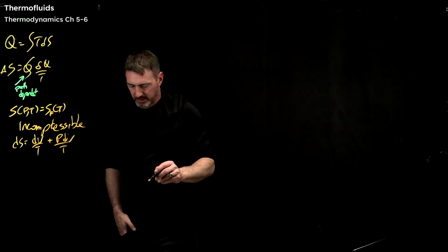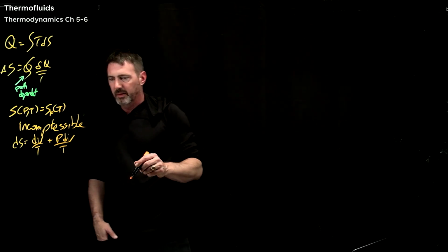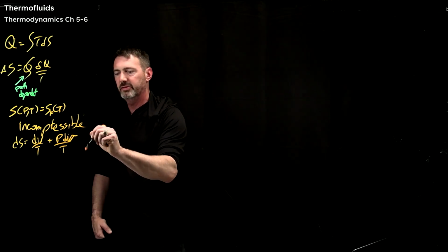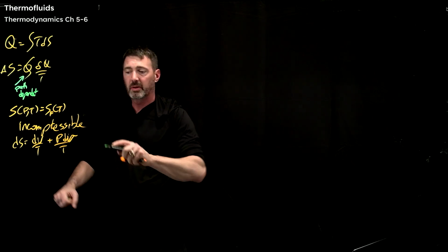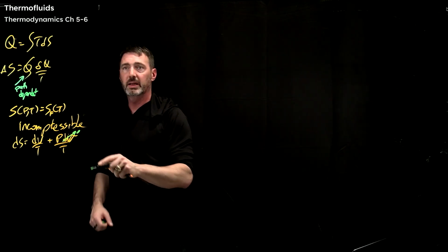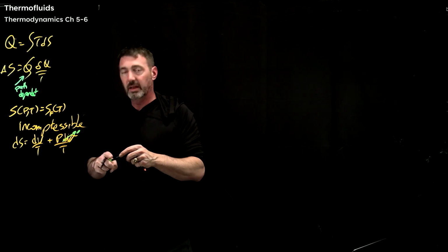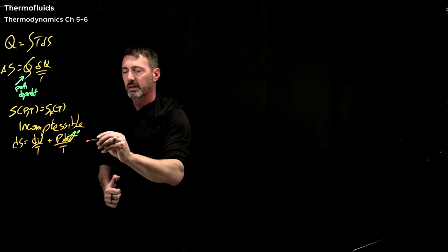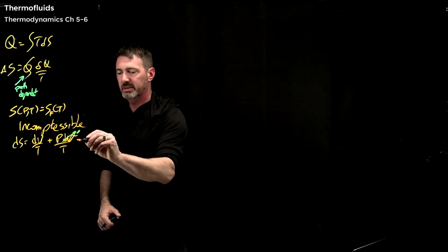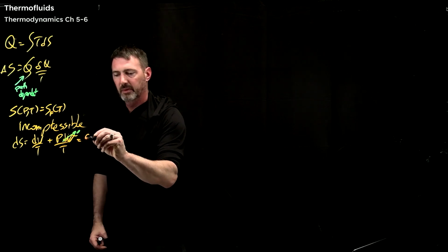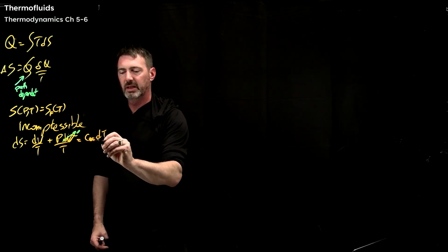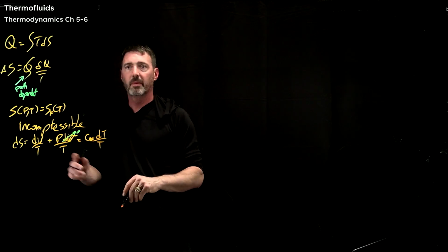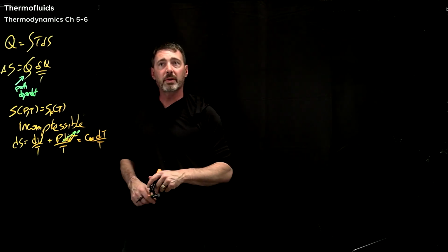That's just rewriting the thermodynamic equation. And so if we are incompressible, and again, this is a change in specific volume, then note that there is no change in density, no change in the inverse density, specific volume. And so this just is this one. And then you might say, well, that's actually just the specific heat, Cv, times whatever that change in temperature is over temperature. Okay, well, that's starting to look like a thing we can integrate.